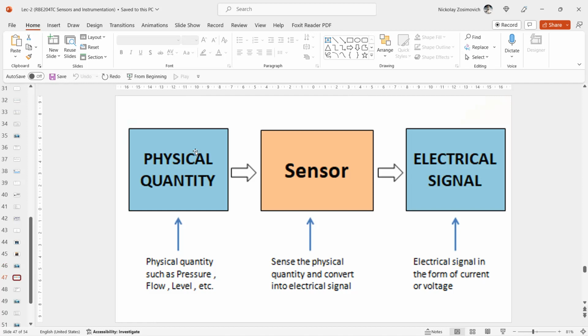First, it's static characteristics, which describe the performance with respect to very slow changes in the measurement. It may be the quantity that has to be measured, and environmental conditions, like temperature affecting the sensitivity or scale factor, offset, and drift. Another group is dynamic characteristics, specifying the sensor response to fast variation in the measurand, like bandwidth and step response.